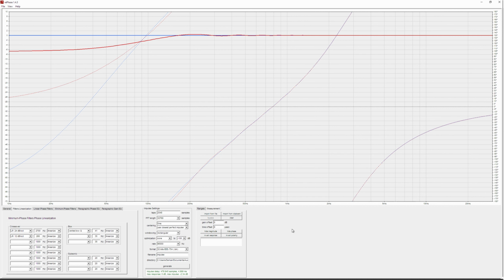So the advantage of biquad filters is that you can use these with no problem the lower frequencies that you cannot touch no matter how many FIR taps you use. I mean, to correctly mimic something like that, you will need at least 16,000. Or maybe if Flex can do this properly. Let's try. Unfortunately, no. Okay, maybe middle and this. Yeah, Flex can do it.